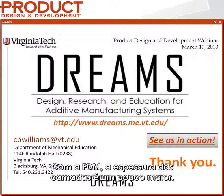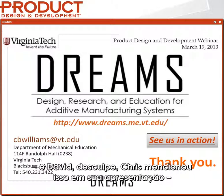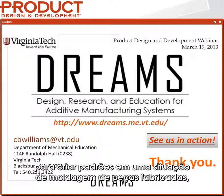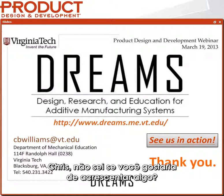With FDM, the layer thickness is a little bit thicker, so you're not going to get as smooth surfaces. So it's tough to quantify from the point of view of what the ultimate capabilities are, but I can tell you that there are plenty of people that actually use, and Chris referenced it in his presentation, parts printed off a PolyJet machine for patterns in a molding situation, both in manufactured parts, as well as folks that have actually used FDM parts in a real production environment. So it really depends on what your needs are. Chris, I don't know if you have things you want to add to that.